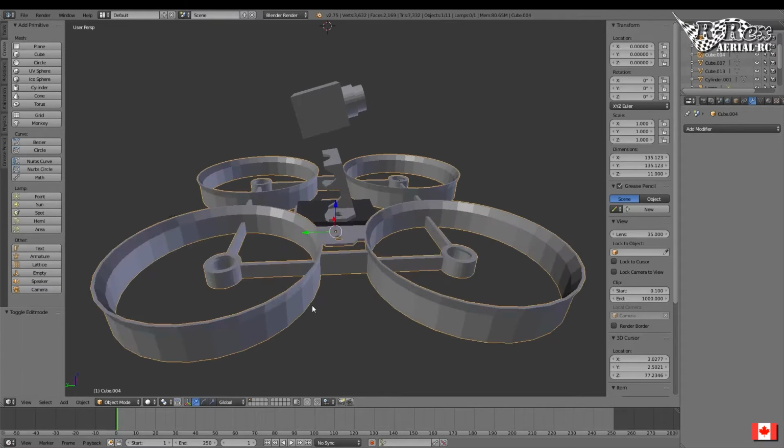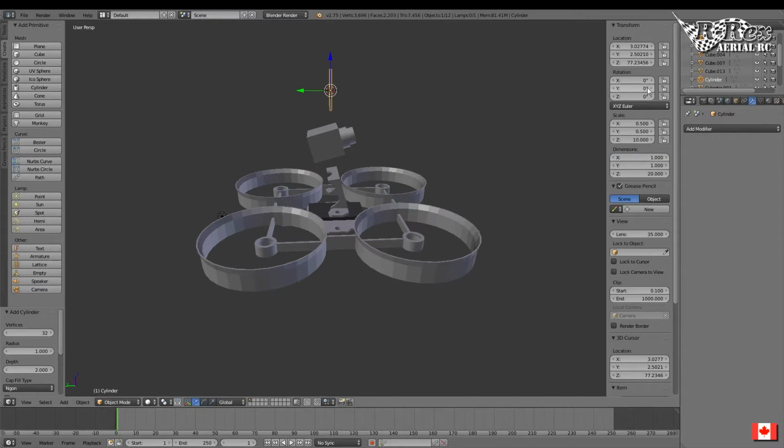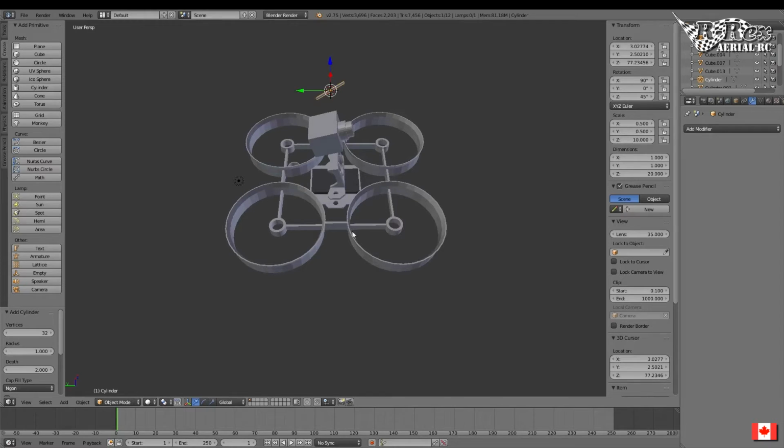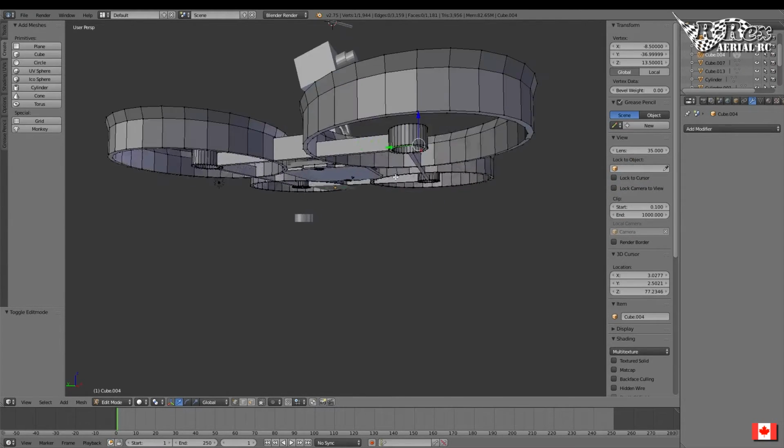So what I want to do is make it so that this surface can come on the inside. To do that, I'm going to create a cylinder. I'm going to make it 1 by 1 and make it, I don't know, 20 mil long. I'm going to put it on its side and rotate it at a 45-degree angle. I'm going to find out what the base of this is, which I believe was 5.5.